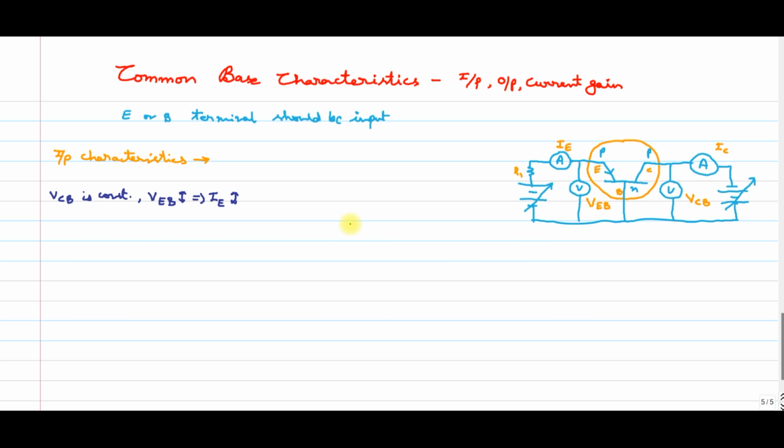If you keenly observe this, it is just like a PN junction diode: giving some voltage to a PN junction diode and obtaining the current passing through it. So how can we deal with this? These characteristics are exactly equal to the forward bias characteristics of the PN junction diode, because here also we are giving forward bias to the input circuit. So let us draw this one.